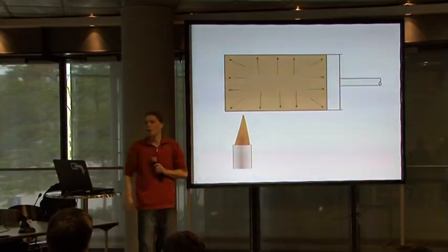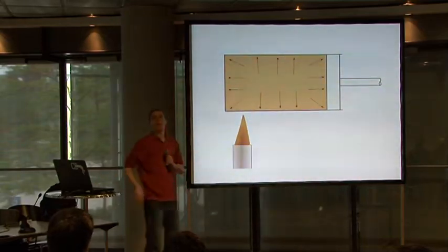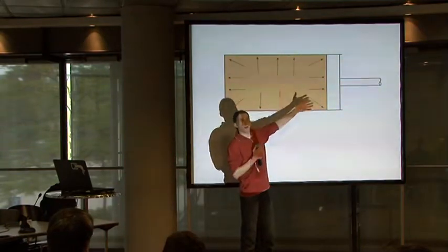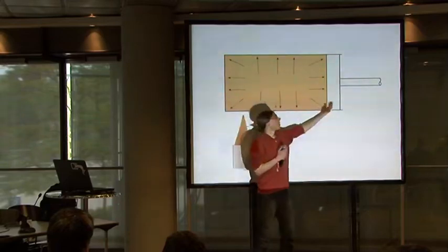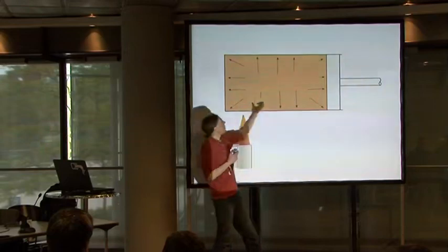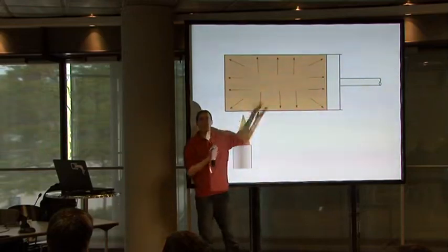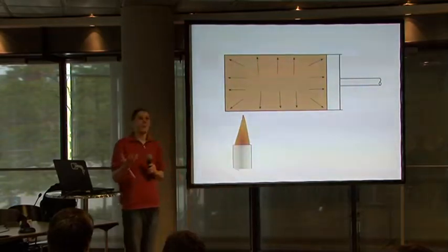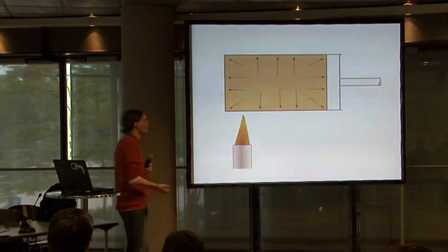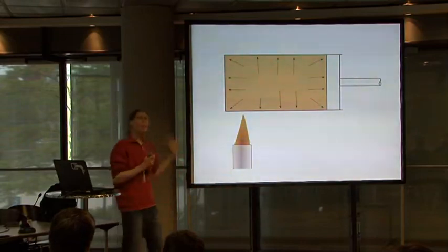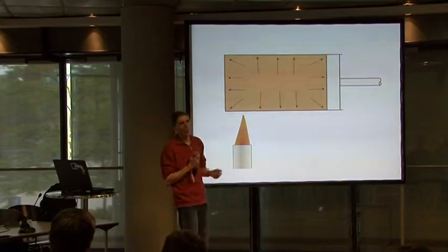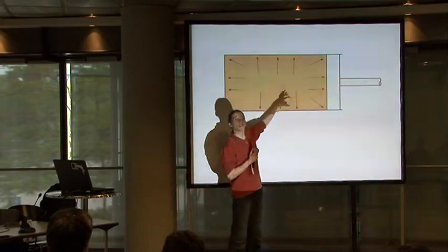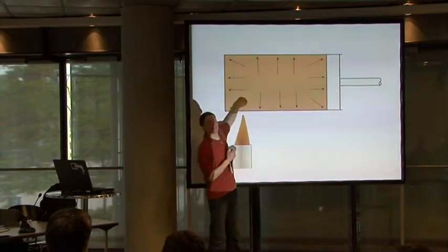But what happens when you're done? When you're done and you've pushed all you could on the piston, and your gas is at mild temperature, and you'd like to start again. What you'd like to do is to get that gas to be at the same volume you had initially, and you want to start again, to do it continuously, for example, in the car engine. And the conundrum of the thermodynamic engineer is that you can't. There's no way to get back to where you were without dumping heat, without removing all the heat that's spread into this gas. So it contracts and gets back to the start.